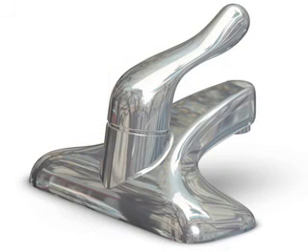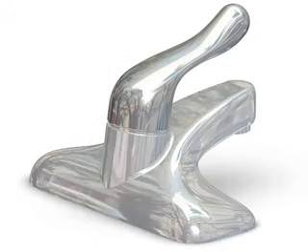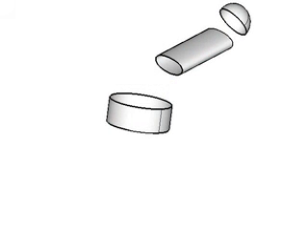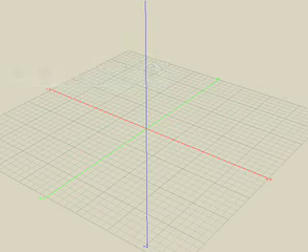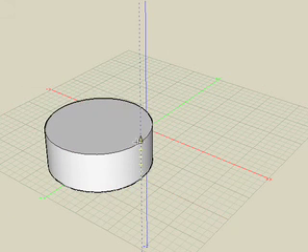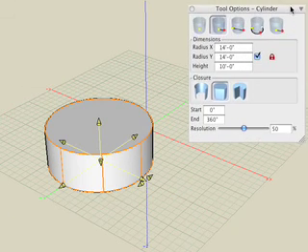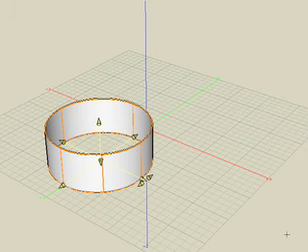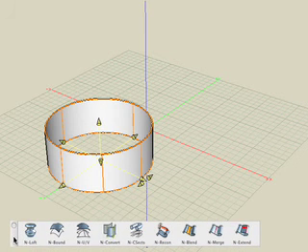Let's conclude this tutorial with a quick example. We'll create just the handle of the sink faucet by blending and merging 3 Nurbs surfaces. The base of the faucet handle is a primitive cylinder. In the Tool Options palette, we can set the closure to be none, so it's open on the top and the bottom. And then using the Nurbs Convert tool, we can convert it into a Nurbs object.